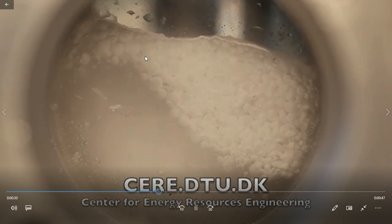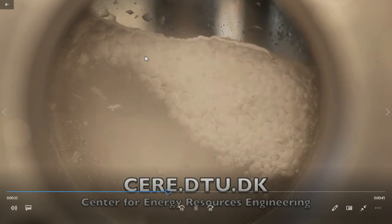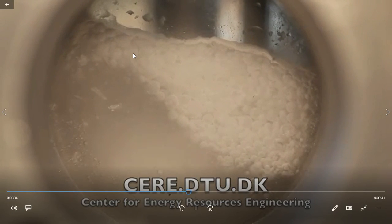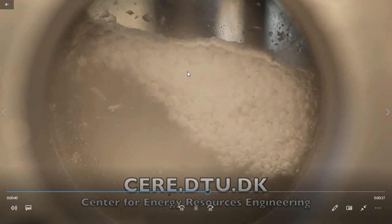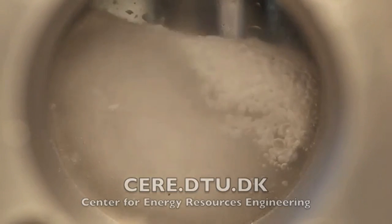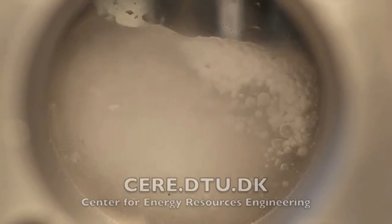Now these hydrate formations, we don't want them. They reduce the diameter, cost us money to remove, and we have to clean the pipeline and stop the operations for a while in order to remove those hydrates from the pipes, especially in offshore. And if these hydrates form inside, let's say, a separator, it can cause a malfunction. So it's more of a problem in offshore wells and offshore reservoirs.